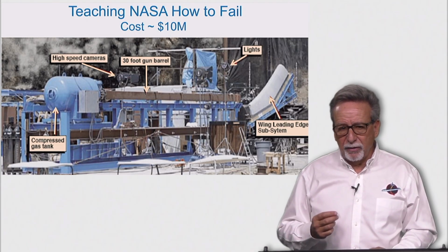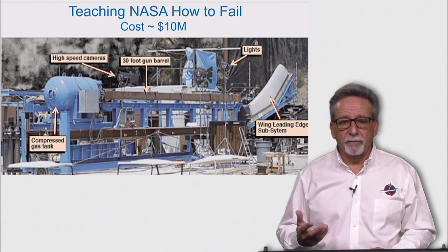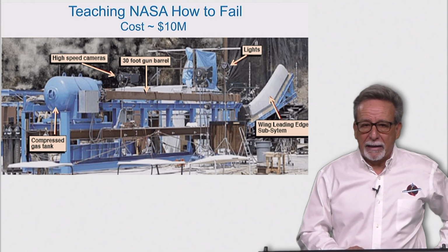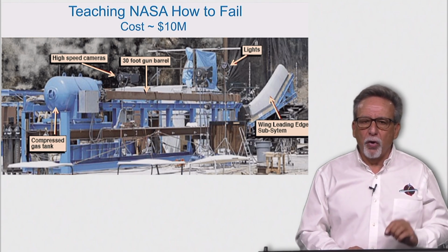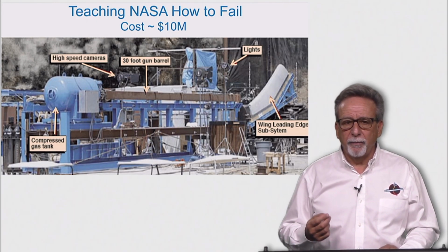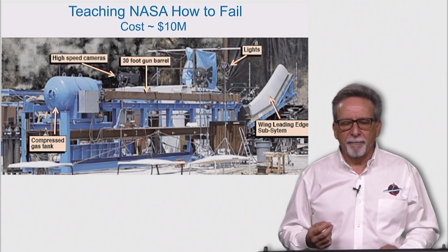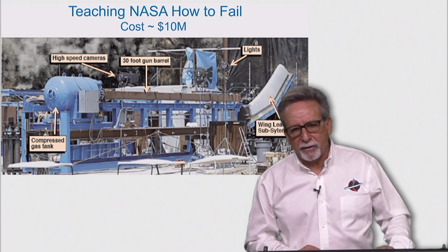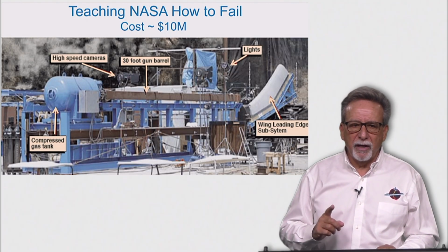The experts initially thought that they needed only 6 strain gauges on this entire vehicle. Totally inappropriate and inadequate. If they did that, there would have been no real data captured which could have helped us develop and correlate a real physics-based ballistic impact analysis. If we allowed these contractors in NASA to proceed, all that we would have learned after this one test was